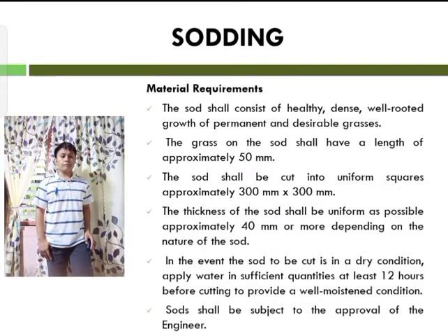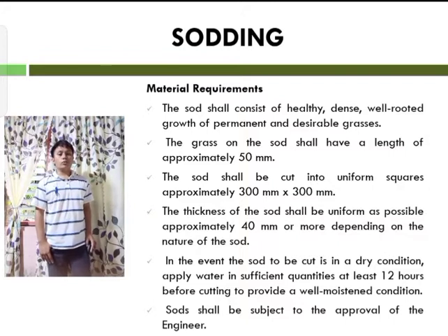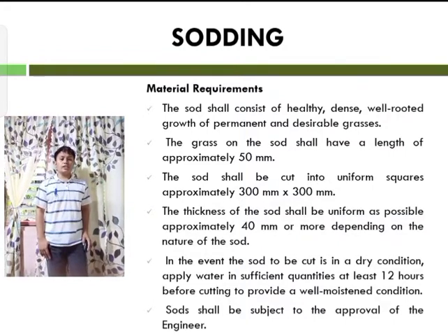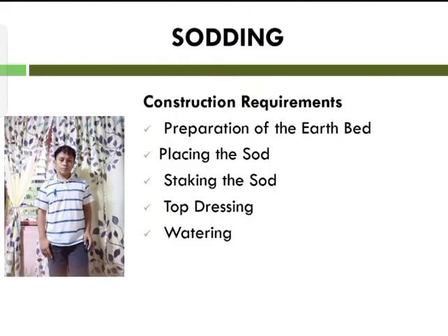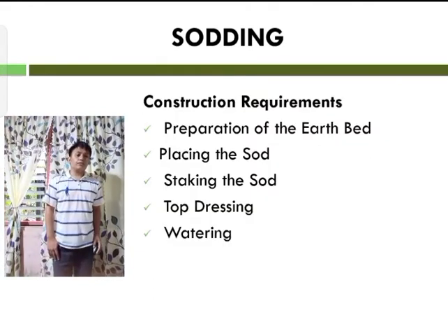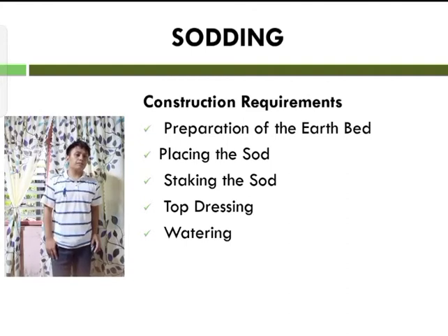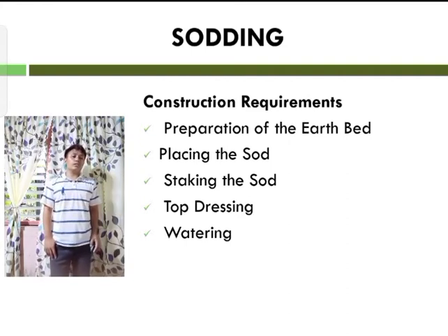of the sod. In the event that sod is to be cut in a dry condition, apply water in sufficient quantities for at least 12 hours before cutting to provide well moistened condition. Sod shall be subject to approval of the engineer. So the next subsection is the construction requirements.